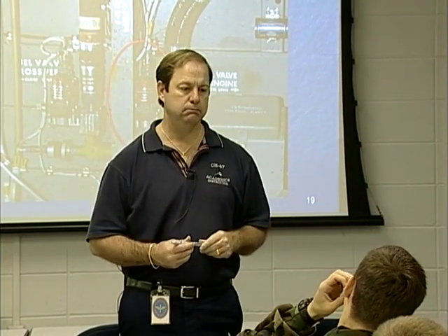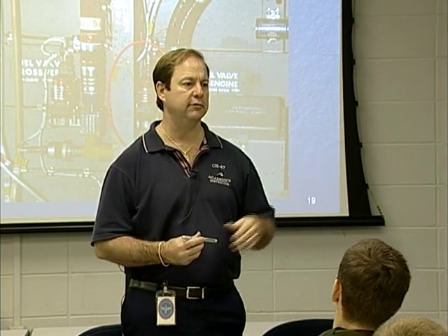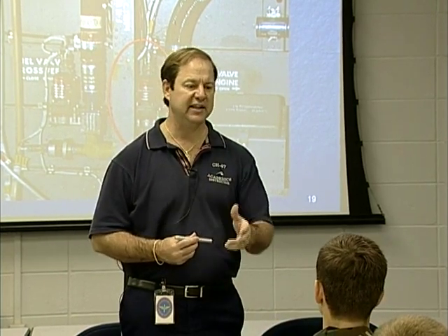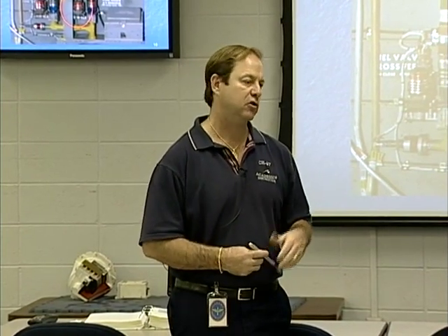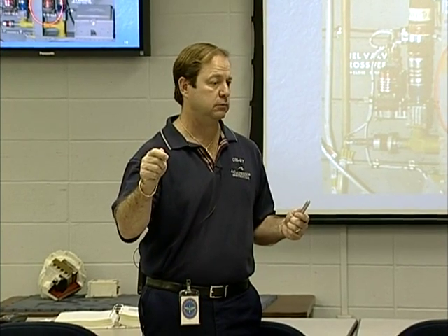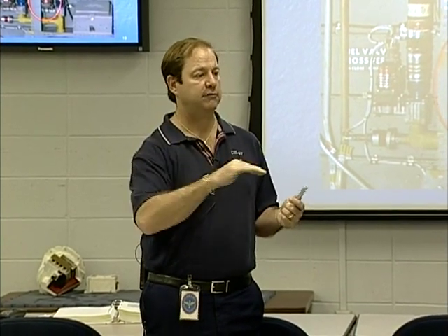And actually, you know what I would do? When I used to train, I used to leave it that way. Why would I leave it that way? Power on it should fix it. As soon as you power up the aircraft, it's going to fix it. And that teaches you two things. So sometimes I would just leave it. And then that way you get the realization that as soon as we apply the power, as soon as you turn the battery switch on, because it works off the essential DC bus, that valve's going to go back to the open position. Why? Because the electrical has priority over the manual.